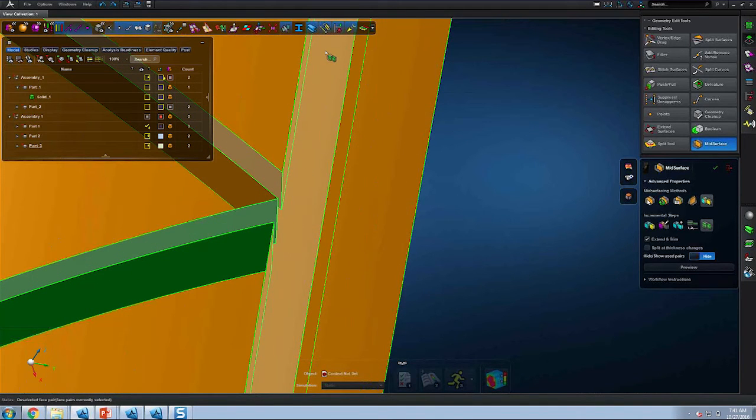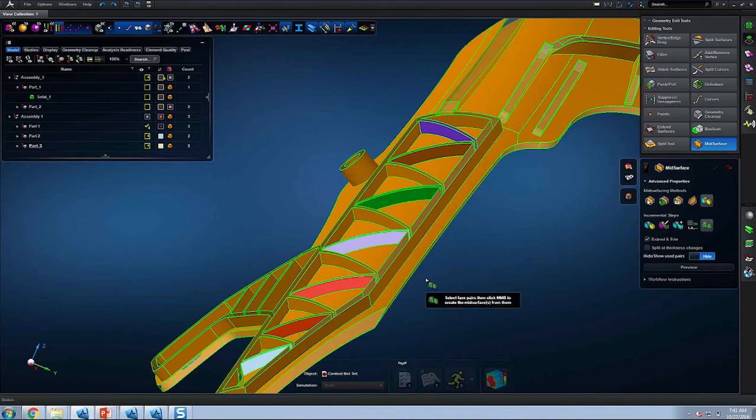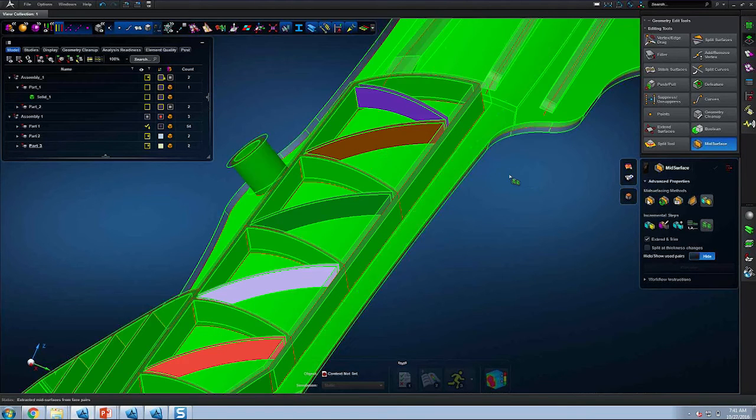Here, you'll have a mid-surface running this direction, another mid-surface here and here. But given the complexity of this model, I'll extract mid-surface pieces for all of the adjacent mid-surface or color pairs, and then I'll address these individual pieces later on. Right now I'm extracting pieces for the other pairs, and here's the ending result.